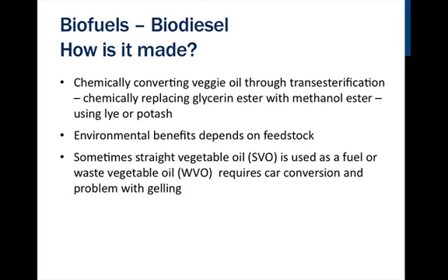Biodiesel comes in a mix of diesel fuel anywhere from B5, which means it is comprised of 5% biodiesel and 95% diesel, to B100, which is entirely biodiesel. The reason for the mix is to avoid the complications of gelling. In northern climates, we get freezing times, which would turn the thicker fuel into a gel. Using a higher percentage of diesel fuel in the mix is advisable during the winter months.